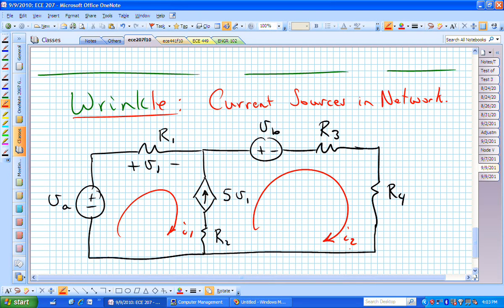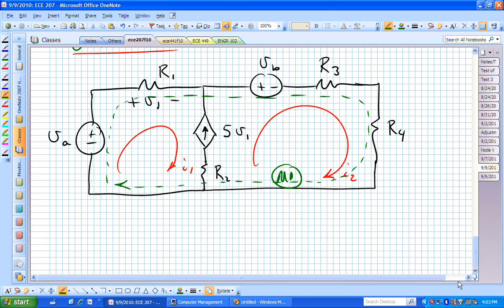What we want to do then is define this super mesh, which says, you know what, we don't have to necessarily go around the little one. We can go around the big one, and we'll call that M1 for super mesh 1. We'll do KVL around that dashed path. We'll just bypass the middle vertical drop, or collection of elements. Is everybody okay with what I'm trying to do?